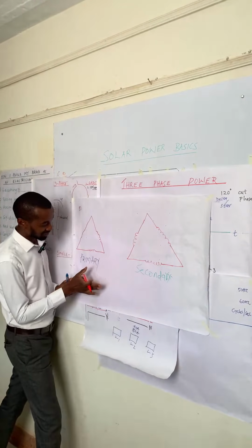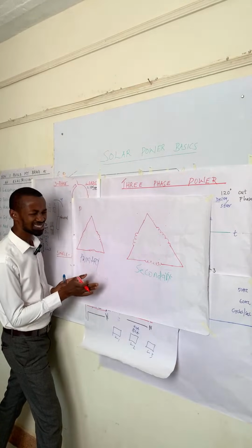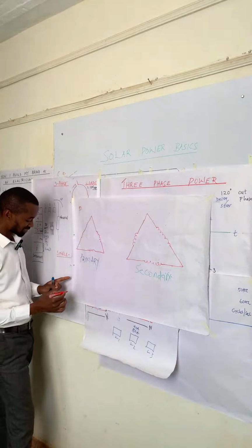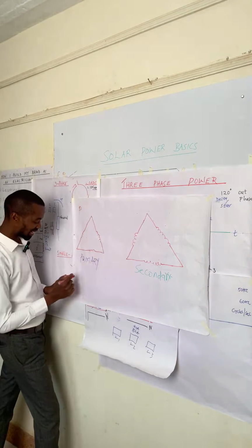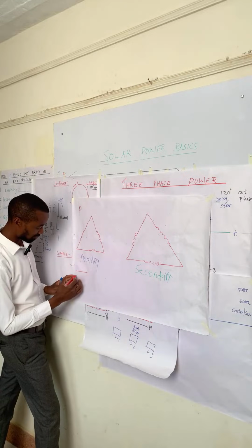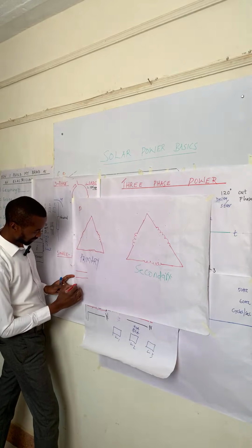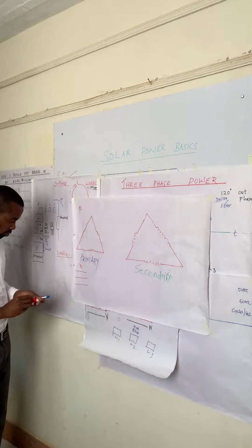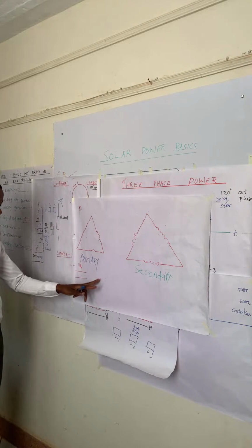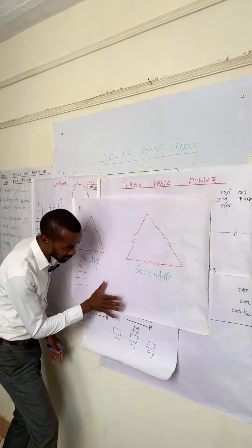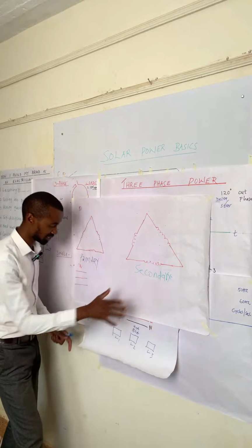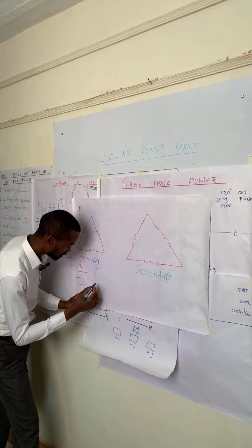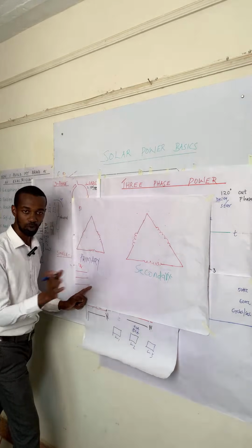This is three-phase distribution like we were talking about. For a single-phase distribution, can it also be tapped from a three-phase power distribution? This is a delta-delta connection. If we have 11 kV and we want to connect single phase customers, who are the majority here, especially in rural setups, we will have a single phase transformer. These are usually pole mounted.